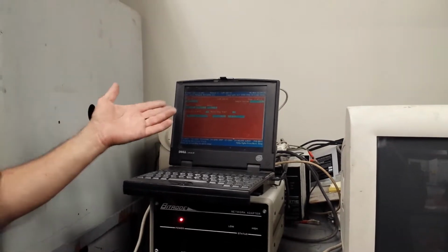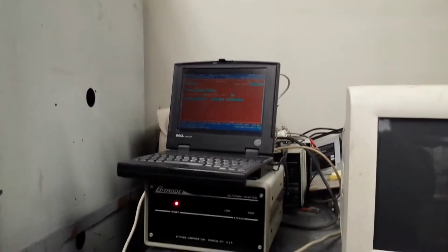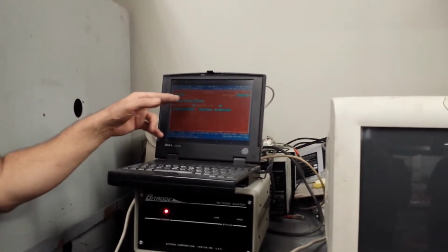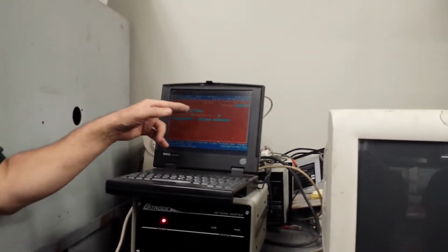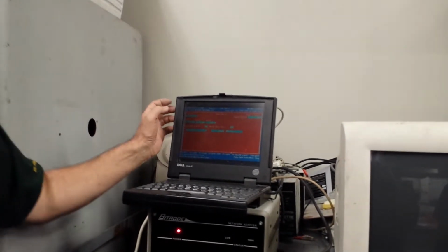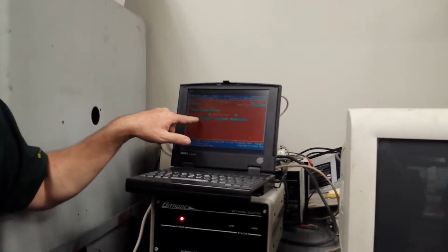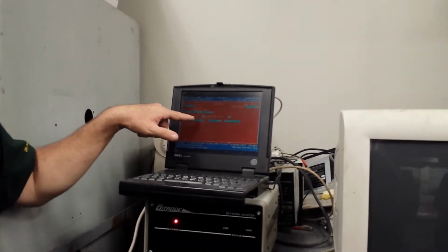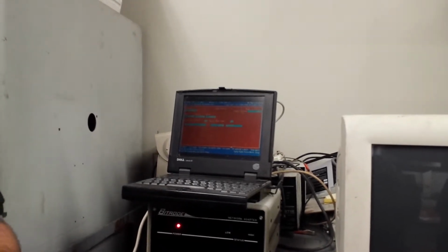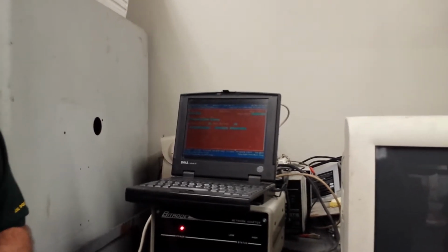Okay, so the volts really doesn't matter here. It's going to limit at 100 amps, because the 100 amps will be reached before we get to that voltage, right? So we're going to discharge at 100 amps, okay? And then these allow you to reset either the amp hours or the watt hours, right? So we really want to count how many amp hours we get out of a battery.